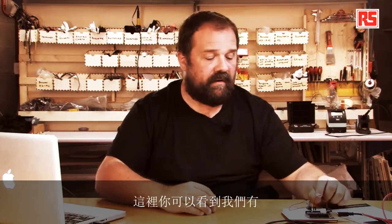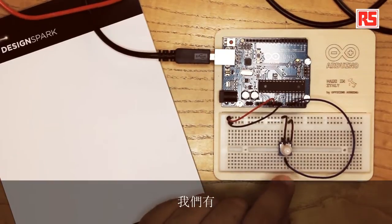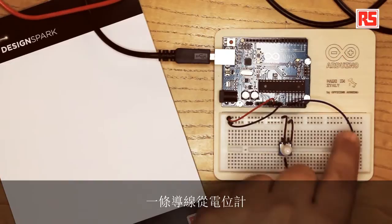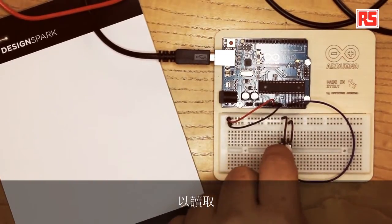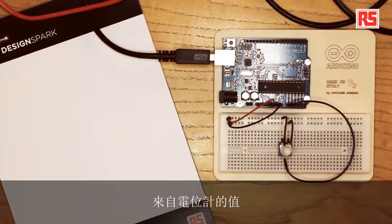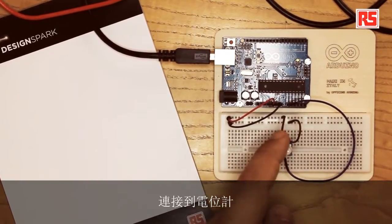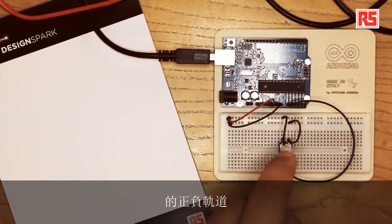Let's build the circuit first. So here, you can see that we have a potentiometer plugged into the breadboard, and we have one wire going from the potentiometer to analog input 0 in order to read the value coming from the potentiometer. Then we have two wires connected to the potentiometer going to the plus and minus rail on the breadboard.